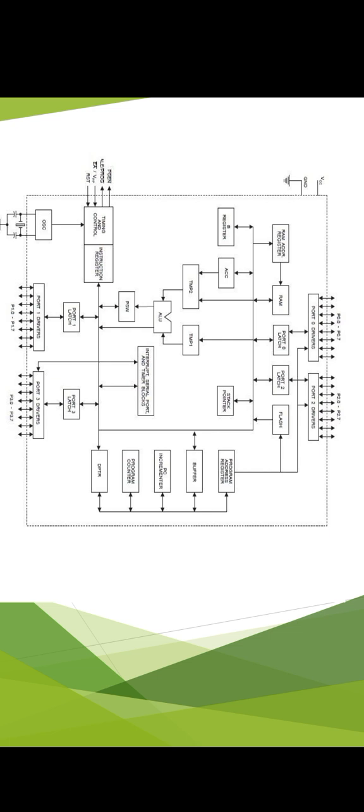in the 8051 classic family. And internal RAM, that is internal random access memory, for read and write, is a 128-byte memory that is indirectly and directly addressable in address space. Register banks are 4. There are 4 sets of registers, each of 8 registers, and these are also part of internal RAM. XTAL1 and XTAL2 pins, these are the crystal pins.